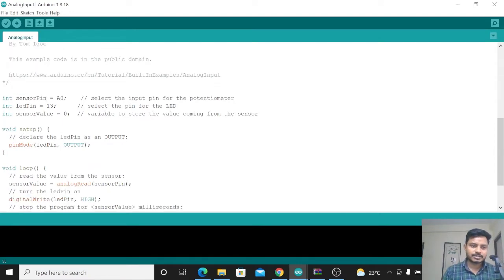Now what I'll do, I'll change it to port value, or I can write here port pin. So port pin is connected to the pin number, as you know that GPIO 26, so I'll write here 26, and our LED is connected to pin number 2 of the Raspberry Pi Pico, and here I'll write port value. So I'm just modifying the code according to our need. Okay, so port value is now 0.